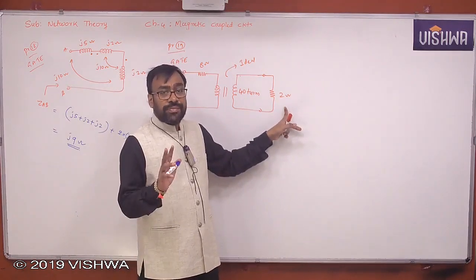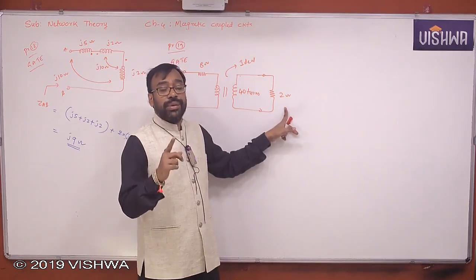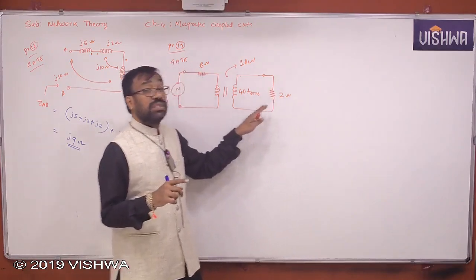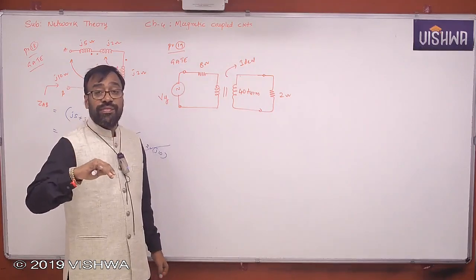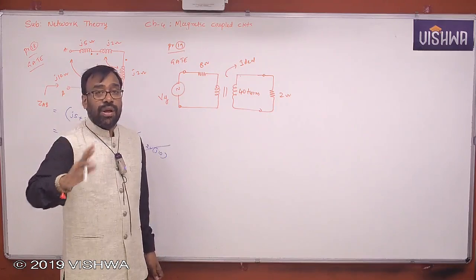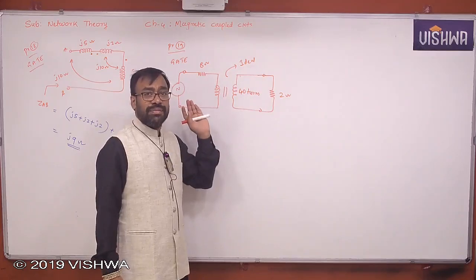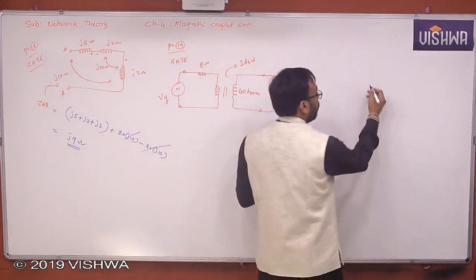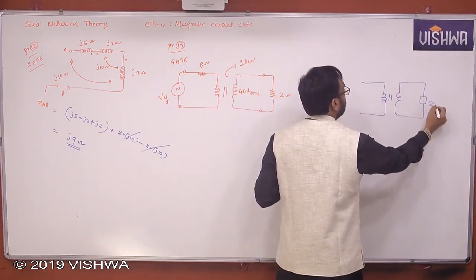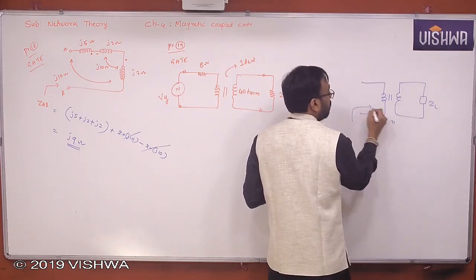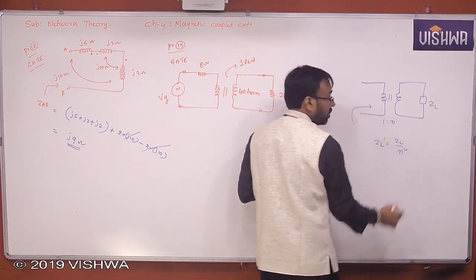But remember, in case of magnetically coupled circuits, better you refer this to primary and then you see whether it is really a function of N or whether it is a variable or not. Understand all of you, okay? So now it looks like constant, but when you refer it to primary, what will happen? You already know that when you have a load on the secondary side and refer to primary side, what did you get? Tell me. Z_L dash, what will you get? Z_L by N square. Yes or no, all of you?